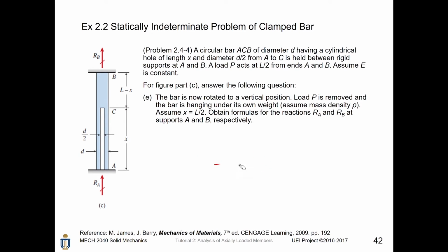However, in this case, we are going to deal with another case, delta equals the integral of P(x) dx divided by EA, from 0 to L. That is, the direct force inside the bar will become a variable of x, while the area will become a constant this time. Let's read this problem.